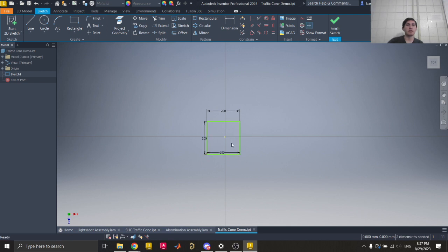One way that you can make that change a little bit quicker is if you have everything all referencing one basic dimension, so that you only have to change one number, and then it updates all the rest, similar to Excel functions. So what I'm going to do is use this D0 right here as my dimension that I'm going to use to drive a few other things.